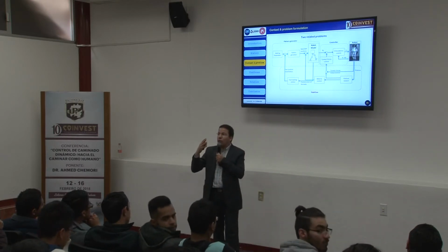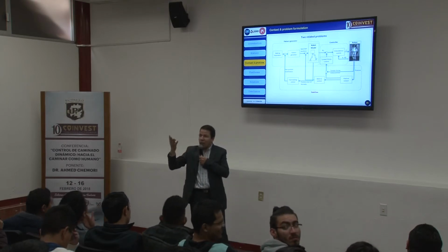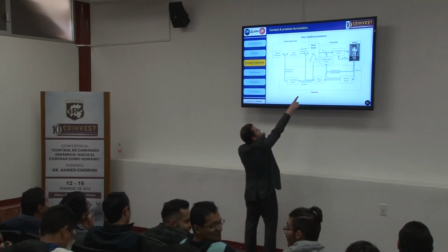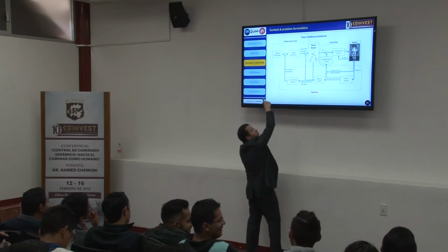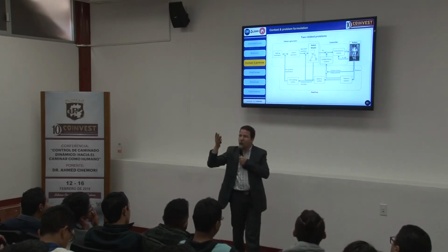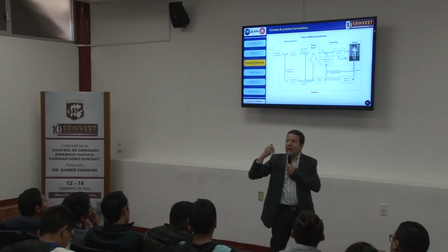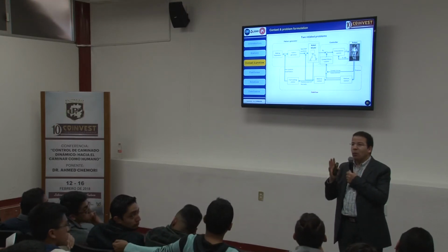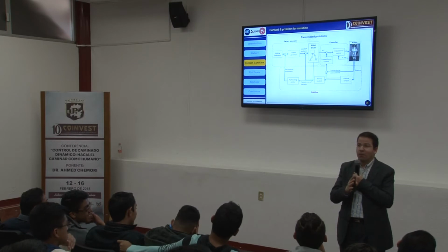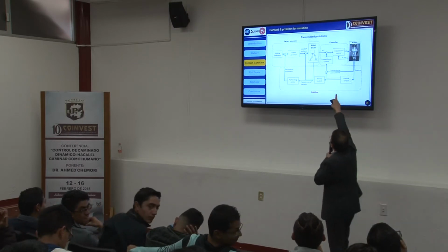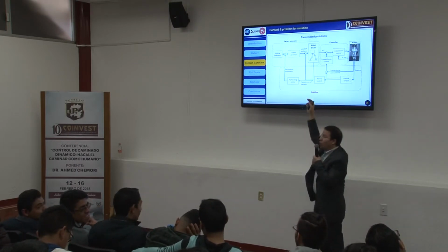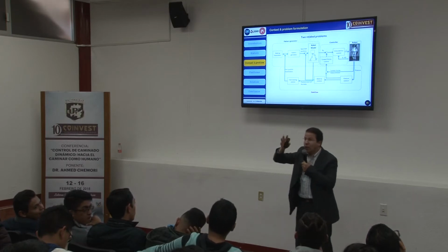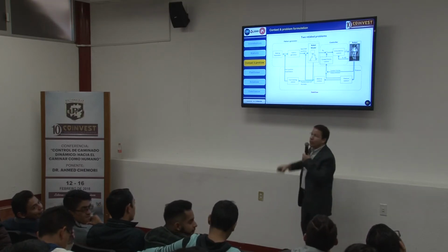And the stabilizer is also another controller. It's like having an inner control loop and an outer control loop. The outer control loop represents the stabilizer, and the idea is to keep the dynamic walking stable all the time. And the inner control loop follows the reference trajectories generated by the pattern generator.